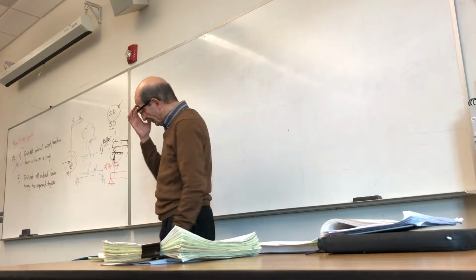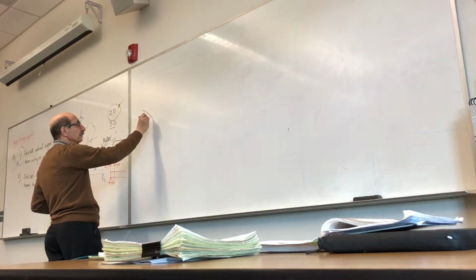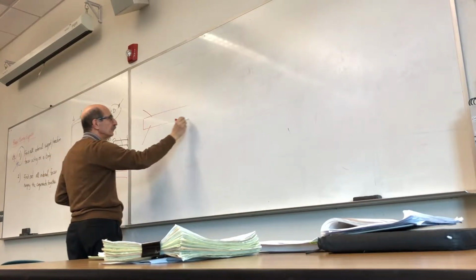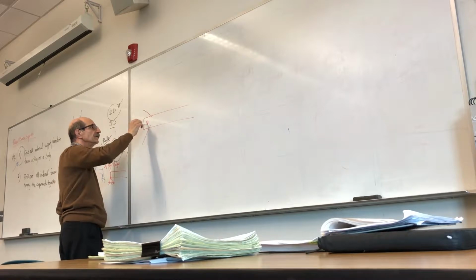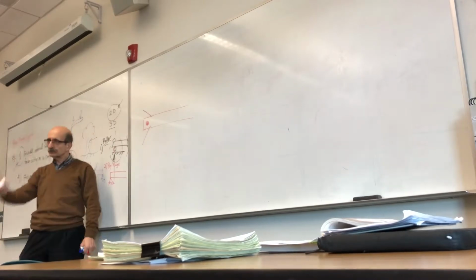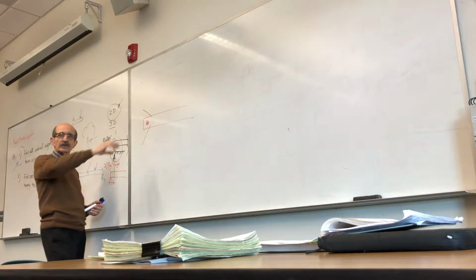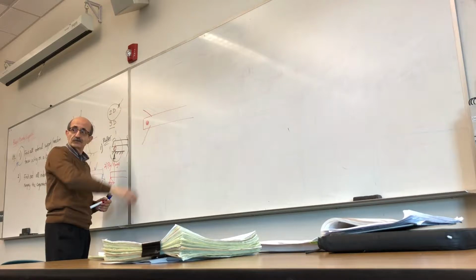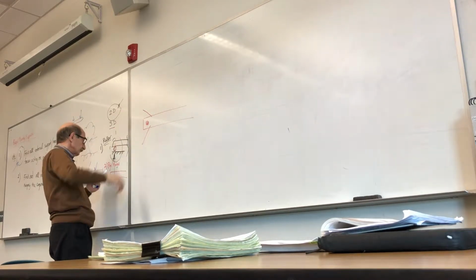Right. But imagine that you have, for instance, something like this. A good example, let's say you have a piece of a board, okay. You just nail that to the wall, just one single nail, right? Yeah. If there's only one single nail, this board can rotate, right? Easily. But it cannot move this direction or that direction, that's a pin.